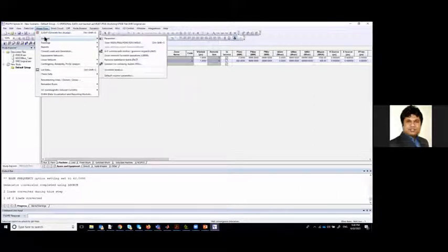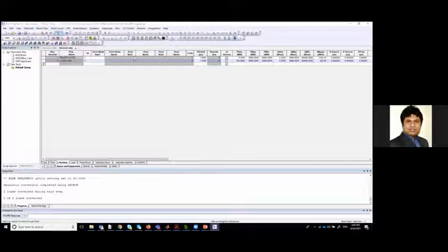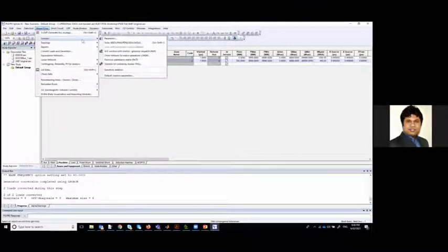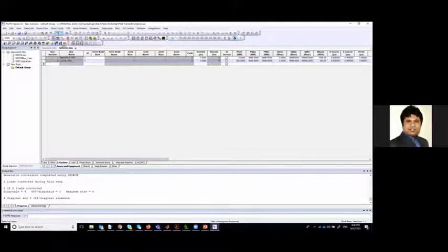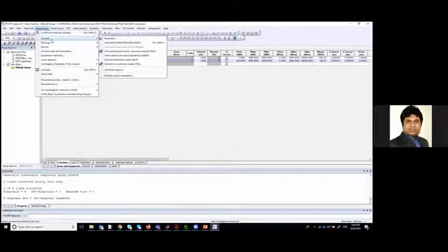Then we go to PowerFlow solution and follow some steps. Order network for matrix operation. That means we make this ready, and when we click on this, it will create a Y-bus matrix. Order network for matrix operation, assuming all branches are in service. Then we need to go again and factorize the admittance matrix. Once we did that, we factorize it.